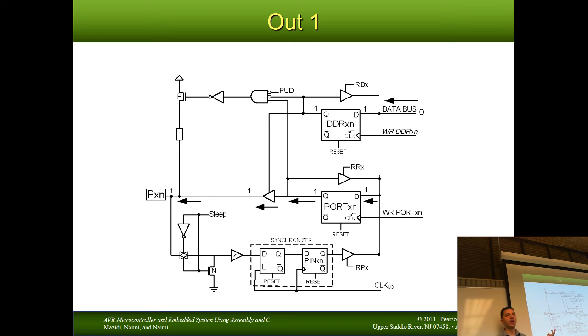Badness happens, right? If we use our Ohm's law, V equals IR, I equals V over R. V is 5 volts. R approaches 0. And when you take 5 divided by something approaching 0, you get an answer that is approaching infinity amps, which sounds like fun. So what would be happening, though? We would be seeing something bad happening here in all likelihood.